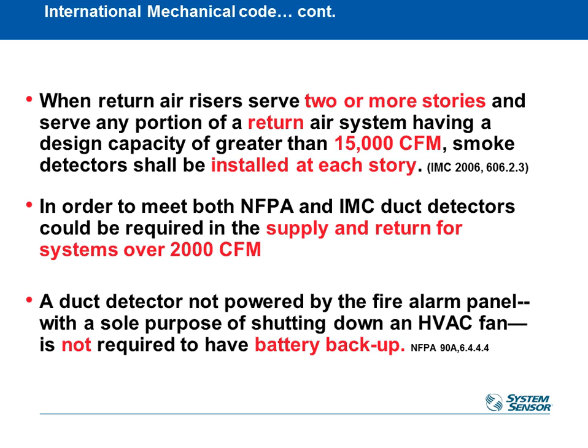And then, like I said, if you are in a jurisdiction that's requiring both the IMC and NFPA, then you will have to put 2 detectors in for 2,000 through 15,000 CFM because you're trying to comply with both codes, supply sensing for NFPA, return sensing for IMC. So you might have to do both.